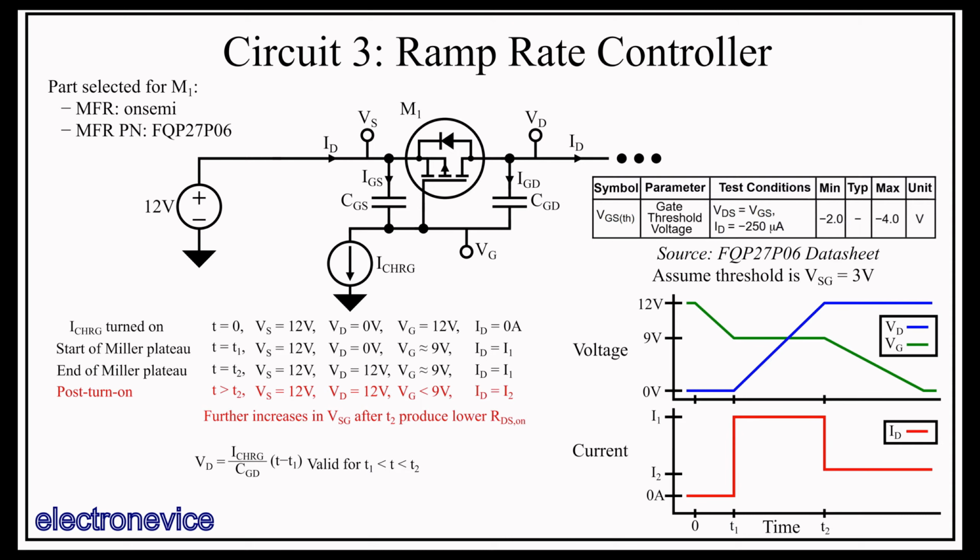So already we see that for a constant gate charging current, we get a constant voltage slope turn-on, and all it depends upon is the value of that gate charging current and the gate-drain capacitance. This is exactly the behavior we want, though the timescales for a MOSFET turning on in this manner without additional external capacitance tend to be pretty short, and the current surge tends to be very high. Also, it's worth noting that the most dubious assumption we've made here is that CGD is constant. It is not. It changes with respect to VDS to a significant enough degree that when calculating MOSFET turn-on behavior,